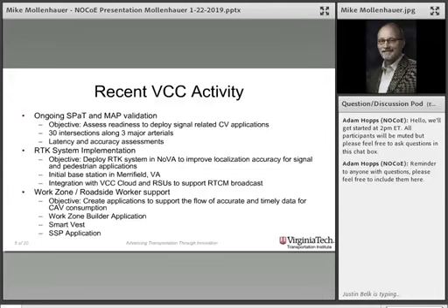Most of the region that we're operating in up there can take those corrections without a whole lot of loss of accuracy or correction effectiveness, just based on distance, because the further away you are from that base station, the less effective the correction is. But regardless, we are currently supporting the broadcast of RTCM messages from that area.